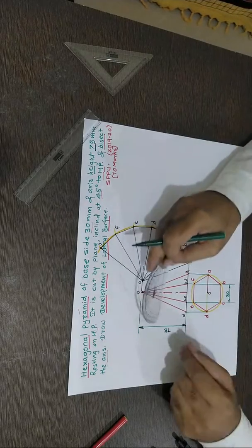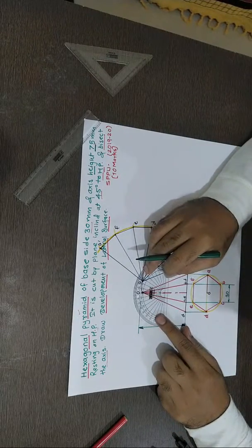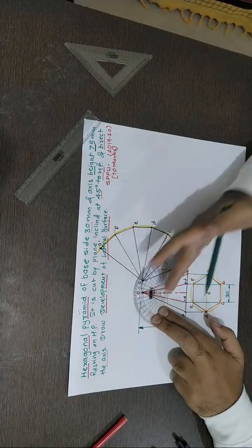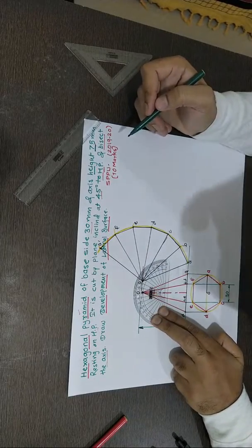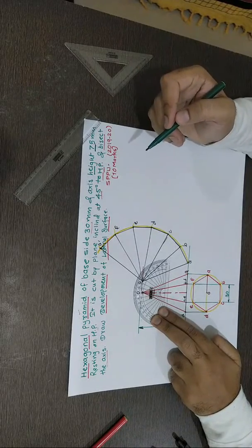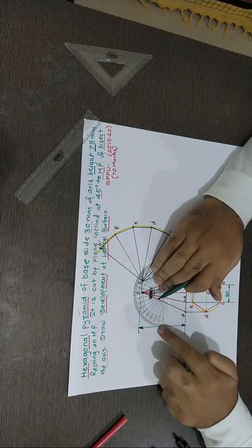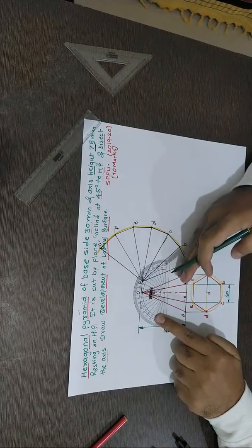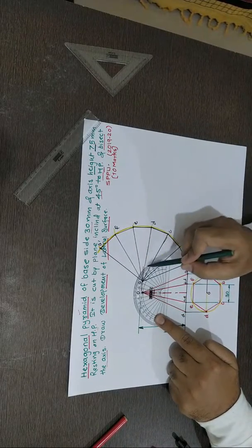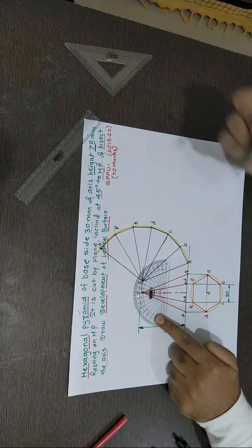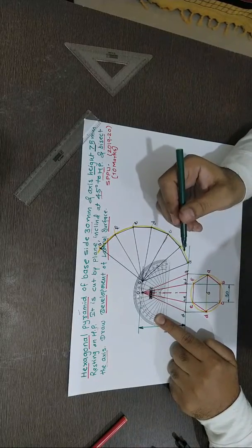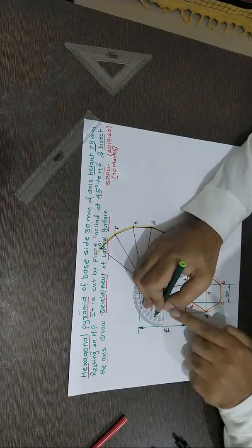Now here I'll keep my D and I'll take an angle of 45. Of course, you can take the angle like this or like this, both are correct. It simply means 45 with HP, bisecting the axis and making an angle of 45 degree with HP. Even if I take it from this side, my plane will be oriented like this, and if I take 45 from the other side, it will go like this. Technically it is correct. So I'll take it from this side.